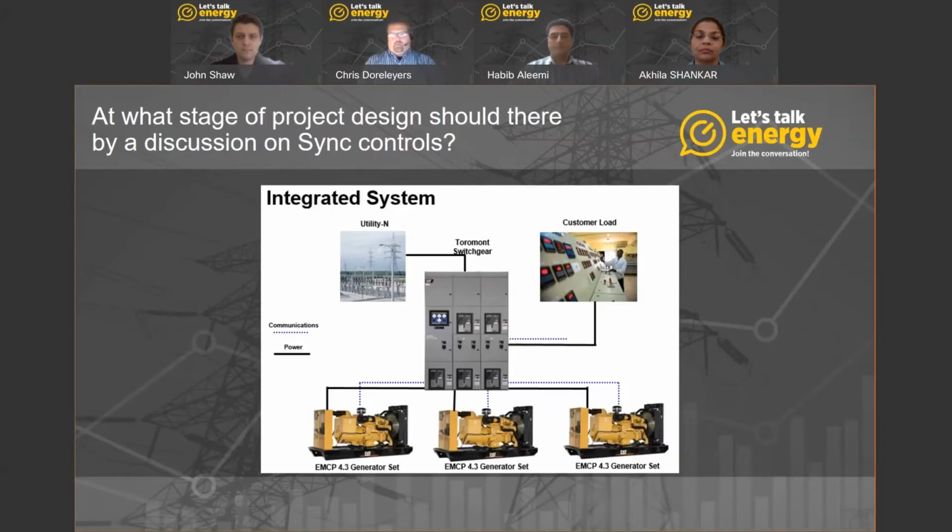Some breakers, depending on if you're in medium voltage, your cycle time may go up. And there are little tricks to bringing that down in a timing diagram, and we can do that analysis ahead of time. So that's one little thing to be aware of for all those online here, that that actually can be sorted out ahead of time. Back to you, John.